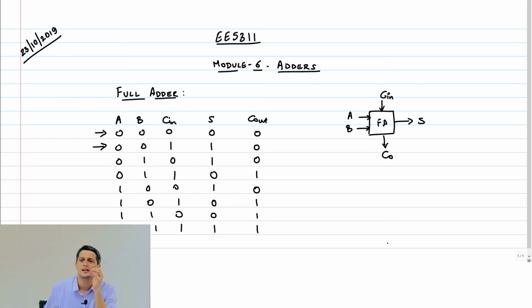It means that irrespective of the input carry, the output is just killing the carry, right? The carry is just gone because the inputs are basically 0, 0. So this is what we are going to call kill, K. Now what happens if any one of the inputs, A or B, happens to be 1, right? That is basically if you see these cases.